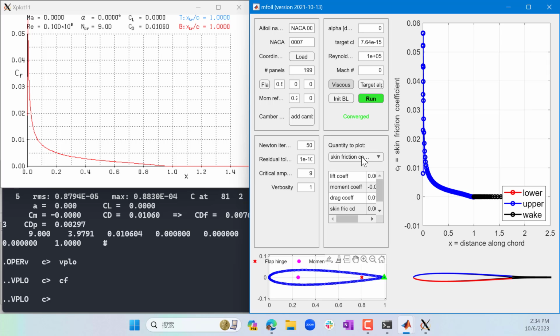So that also tells you viscous flow over a boundary layer is going to give you non-zero drag. So actually the drag comes from 2 parts. One is from skin friction, right? The skin friction is in which direction? What is the direction of the skin friction on the airfoil?